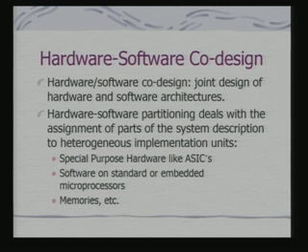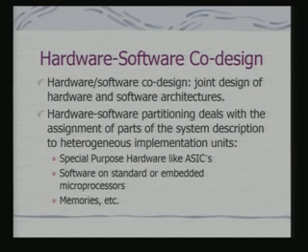Now, mapping into hardware means designing or use of special purpose hardware like ASICs, or it may even be mapped onto FPGAs, and FPGAs are also used for rapid prototyping. If we are talking about the software, the parts or the tasks which get mapped onto the software are being mapped onto a standard embedded microprocessor or a microcontroller. So, the software part of a task is typically mapped onto a standard microcontroller that you are using.